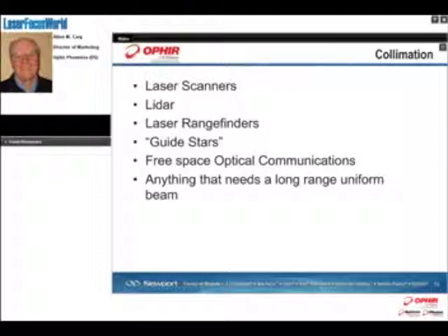Now, collimation is sort of the opposite of focus. So what we're trying to do with collimation is to extend the laser beam into a long-range type of usefulness, as you will, thinking of the beam as maintaining a size, a useful size for a long distance. Now that can be a relatively short long distance, like say with the scanners that work at point-of-sale, like in the grocery store. There you want that beam to work over a range of a meter or so, so you don't have to hold the barcode exactly in one spot.